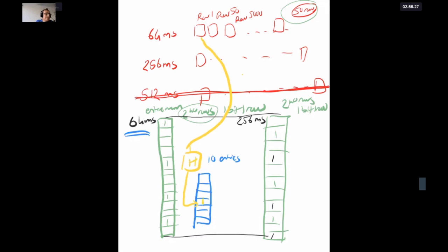And okay, I insert row 1 to this location because the hash function tells me that whenever I need to access the Bloom filter, I go through this hash function so that I can distribute the bits relatively equally in this Bloom filter. So I basically populate this Bloom filter with the list of rows or addresses of rows that need to be refreshed every 64 milliseconds, right? So if you have 50 over here, we'll have maybe 50 over here. So 10 entries may not be a good idea. Let's assume that you have 100 entries over here, right? Okay, you determine the size of the Bloom filter such that not everything is a 1 over here.